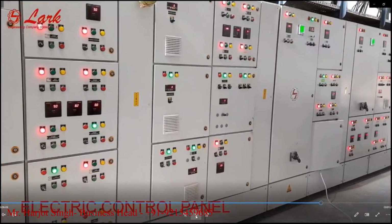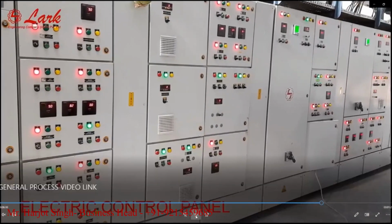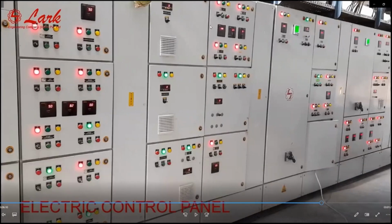Then your electric control panel must have all the features like single phase, double phase prevention, and a reverse RPM prevention system should be there. The rating of the starters and the contactors should be as per the matching of the screens. And one thing more,